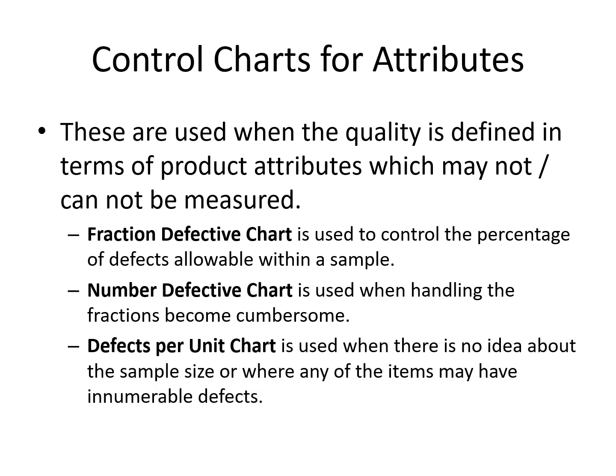And finally, we have the defects per unit chart, or the C bar chart. This comes into play when we do not have any idea about the sample size or there are no uniform samples which can be attained. Or it could be a job shop kind of production where the production happens based on the order. Maybe at times 100 have to be produced, other times 5, next time maybe 30. So each time one gets a different number of samples.